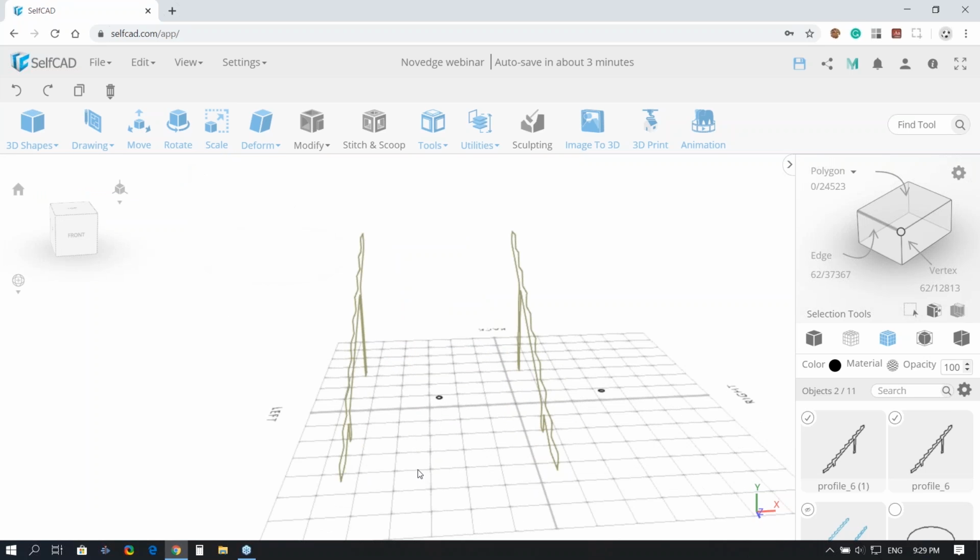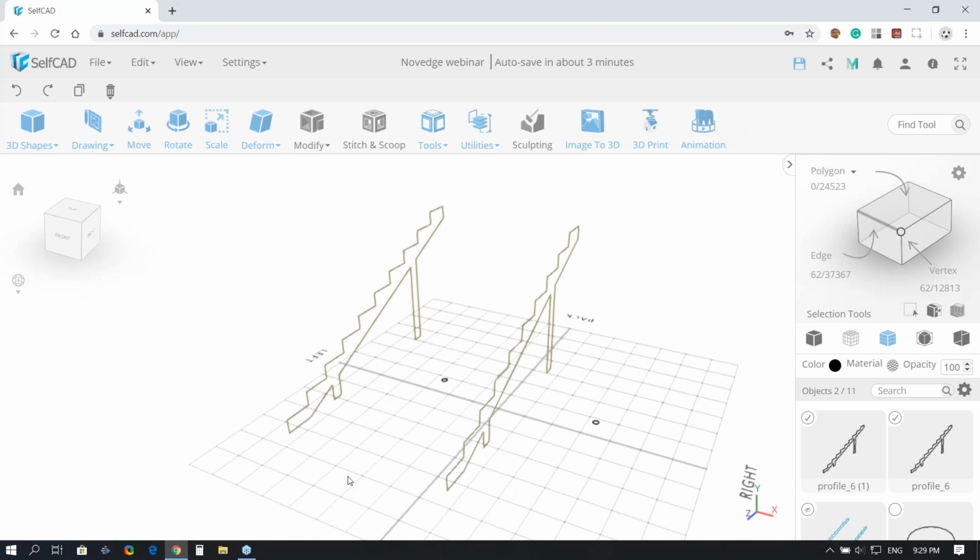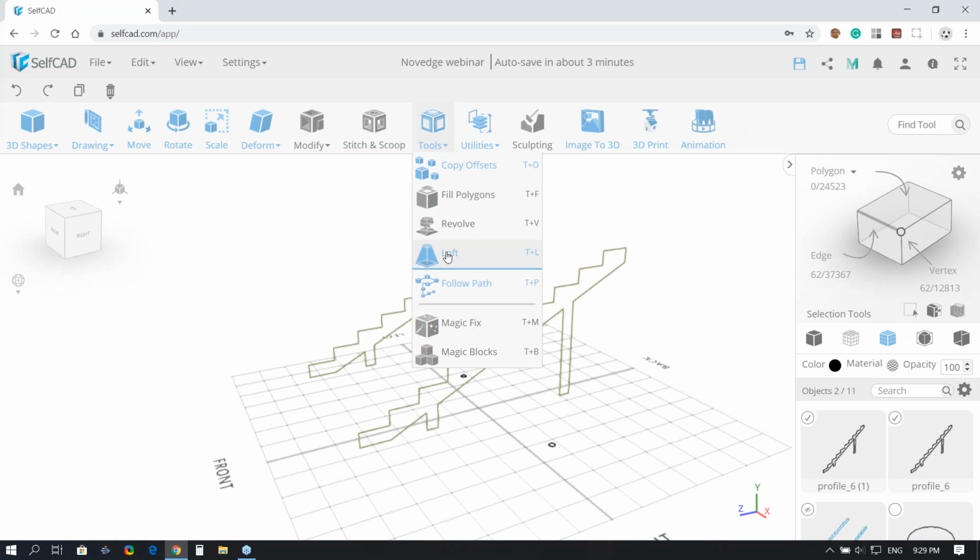So now what we're going to do is I'm going to go to the Loft tool, and Loft basically has options to fill settings. You can have a closed loft, you can fill which direction you want to fill. You can kind of leave it open, then add thickness and different options. For now, I just want to fill both of them. You can add the smoothness, which if I add 5, this means it will have 5 directions in this way. So if you want to add some more details, that would be good. But for me, 1 would be fine in this case.